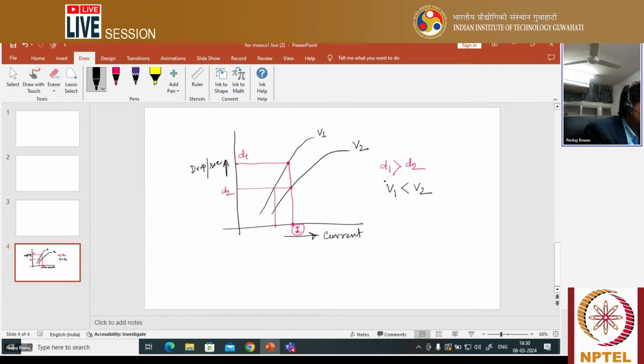That means lower the voltage, higher the drop transfer rate, and higher the voltage, lower the number of drop transfers. This you should keep in mind. But for increase of current, like from here to here, if you increase the current, you can observe for each and every case, keeping all other parameters constant, like for a particular voltage, your drop transfer generally is increased. This is generally the curve for drop transfer rate with the variation of current and voltage. Okay, this you should keep in mind.